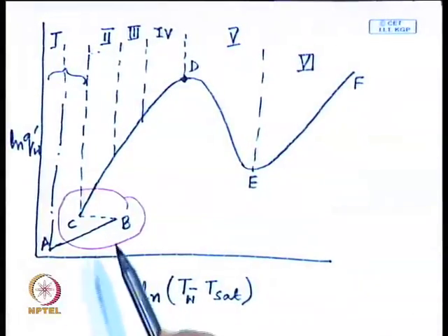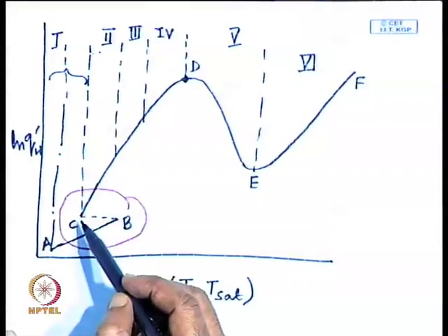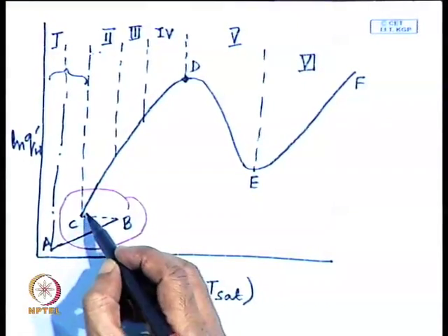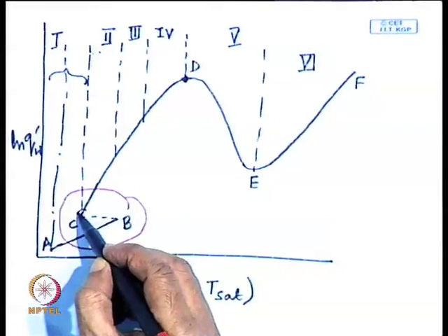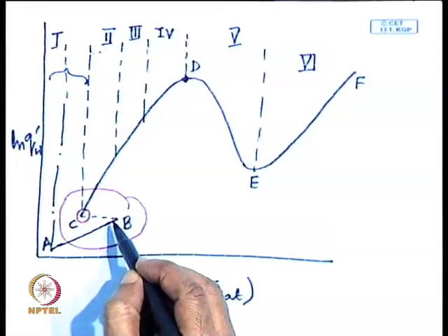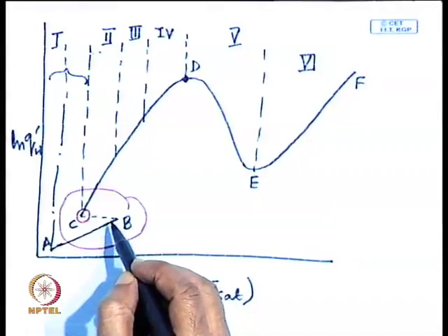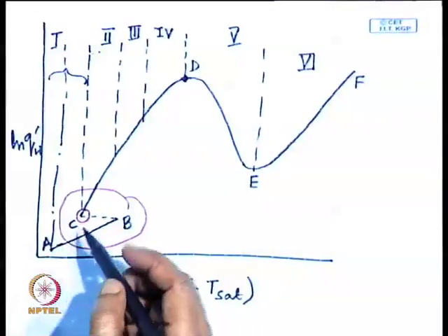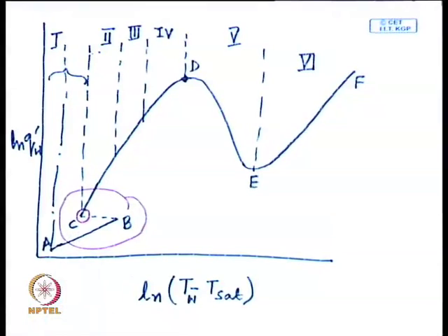It will come back here to indicate that the actual inception of boiling is at this point. By a very controlled experiment, one can find this kind of change in temperature, so that at the same heat flux we get a higher value of heat transfer coefficient.